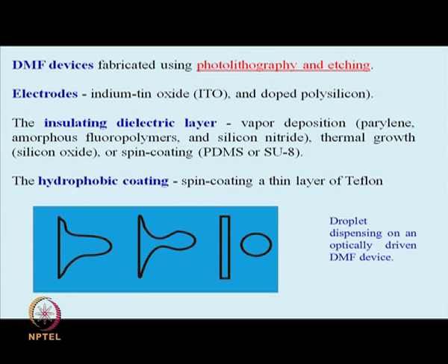Let us say in this figure you can see that a droplet sits on a surface, and we shine a green laser on some portion of it. From a large droplet, exactly like what you do in electrowetting EWOD, you can extract a droplet, because the contact angle changes, and the tendency of the liquid would be to move from the larger drop to the region where the contact angle is less.